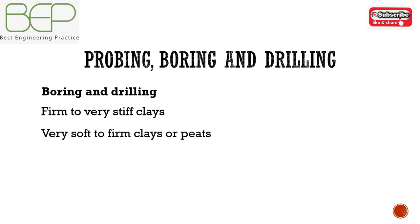Very soft to firm clays or peat. Thin wall piston drive samples may be taken at 1 to 1.5 meters, or if laboratory tests are required, or alternatively in-situ vane tests can be carried out to obtain undrained shear strength.